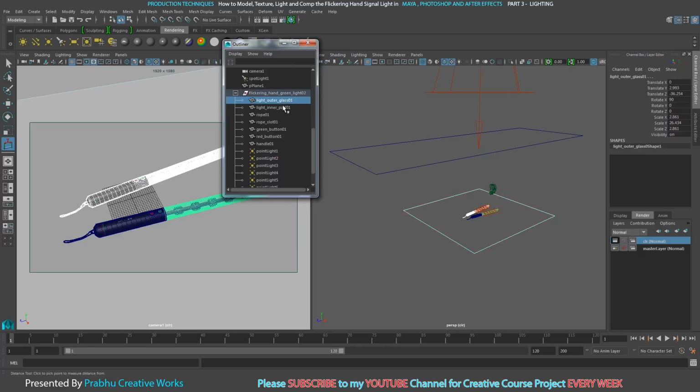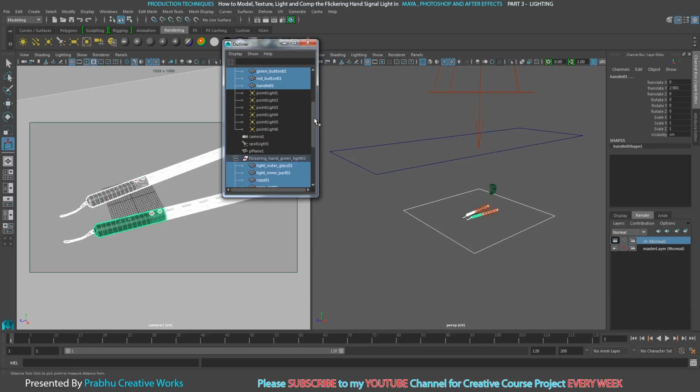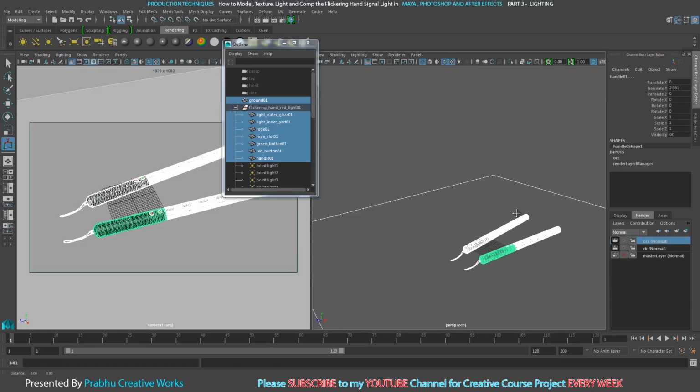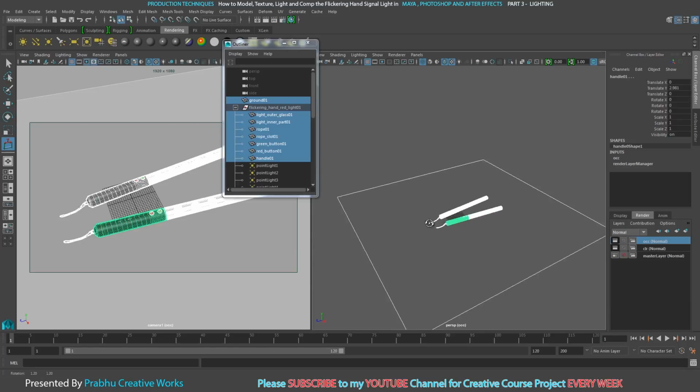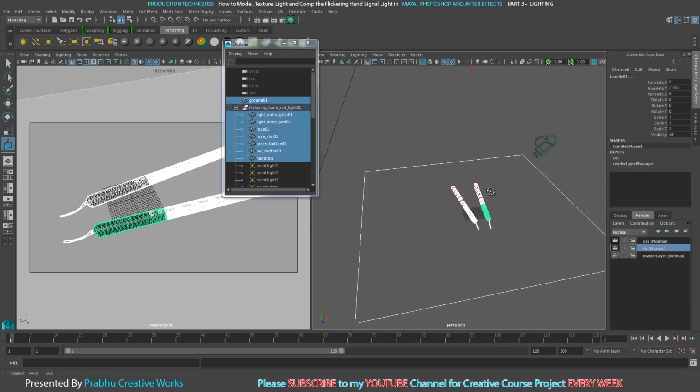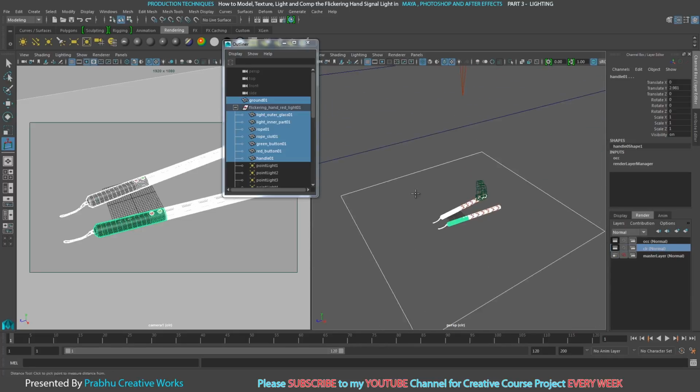You want to select only our meshes. Don't select the point light and click this last button. And then rename this layer as OCC. So occlusion. So I will double click OCC and press enter. So see here, in this layer we have only this mesh, no lights and no reflected surface, only our mesh. So in this color pass we have all things enabled.